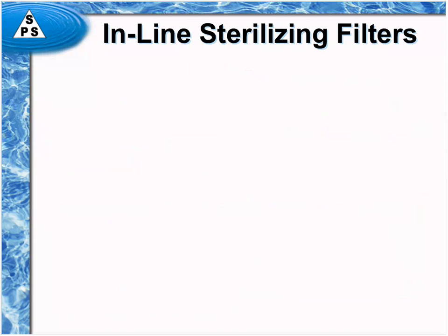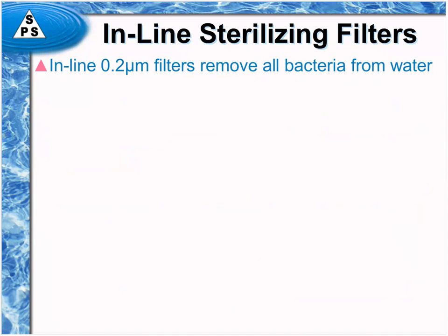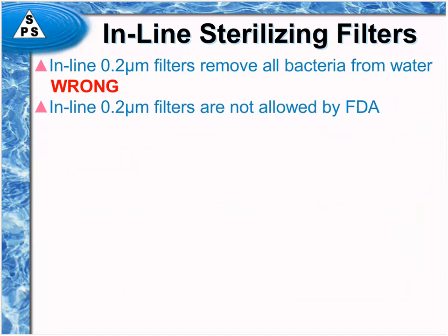Okay, let's talk about inline sterilizing filters. There is a myth that inline 0.2 micron filters remove all bacteria from the water. It's wrong. Even though they're sterilizing grade filters, and even though they're considered to be absolute filters, they don't remove all the bacteria, especially from a water system, because the water bacteria are a little special guys.